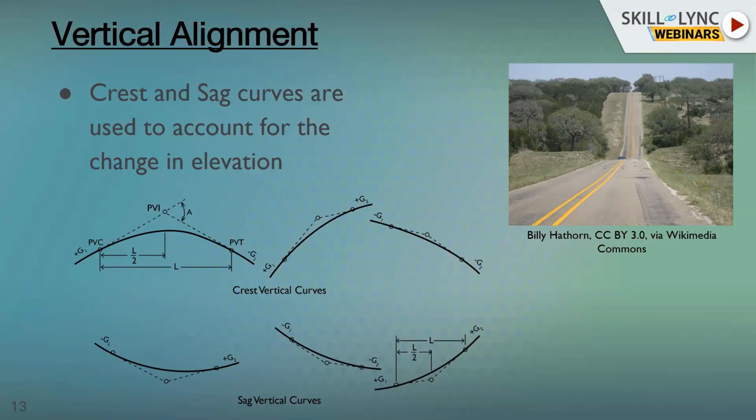So for a particular design speed, you should have this k value, which is also referred to as the smoothness of the curve. The higher the k value, the smoother the curve will become. If the curve is smoother, you can see more distance. If more distance is there, the sight distance is addressed. If sight distance is addressed, you have done a good job in vertical alignment.